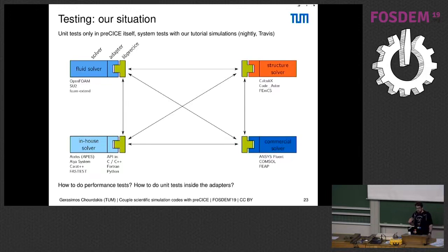However, now we also want to make it easy for the user to start playing with it. So we make these so-called adapters for solvers, which can either be a plugin, like for OpenFOAM, in which case we also need to support several versions of OpenFOAM, and that's quite painful, or to give adapted codes, for example, CalculiX. And at the same time, this should be able to work with commercial solvers or with in-house solvers and so on. And we have 4 different APIs to maintain, more or less.